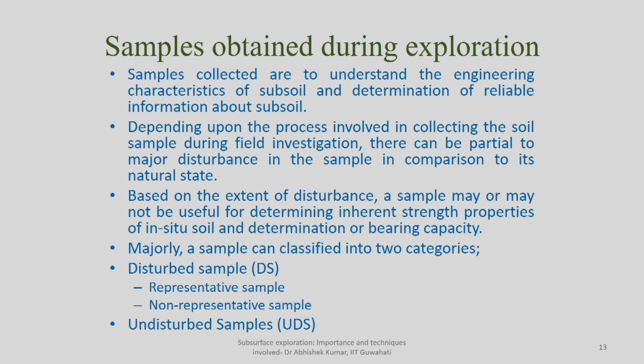So, you cannot call the sample which is brought onto the surface by means of slurry usable for determination of engineering properties. That is why I am saying that, depending upon whether there is partial or major disturbance, it will be decided whether the sample can be used for determination of different properties of soil at that particular depth. Based on the extent of disturbance, a sample may or may not be useful for determining the inherent strength properties of in situ soil and the bearing capacity.